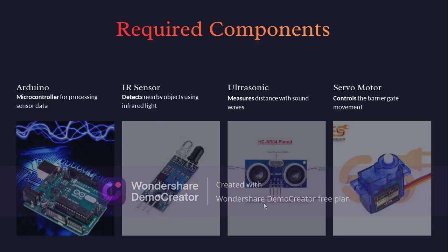Then we are using the ultrasonic sensor to measure the distance of an approaching vehicle. The sensor works by sending ultrasonic sound waves and measuring the time it takes for the echo to return, and based on that time the Arduino calculates the distance.